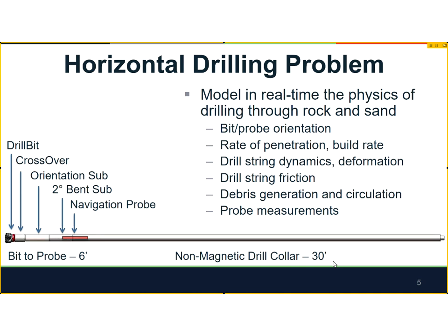And at that point, if you create a closed volume and you're pumping high pressure fluid in that volume, it's going to find the path of least resistance, which sometimes is straight up to the surface. And so that can cause a degradation in the quality of the hole, and they lose fluid, and so that's another scenario which can be catastrophic and require scrapping an entire project and starting over.